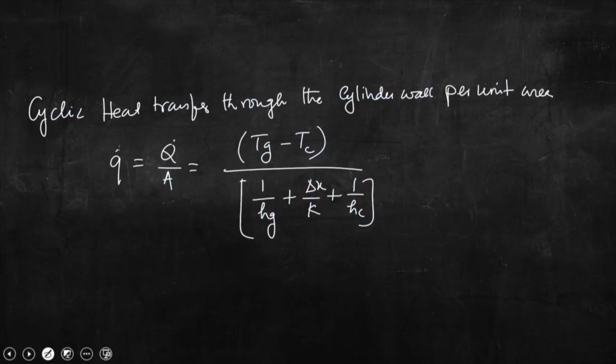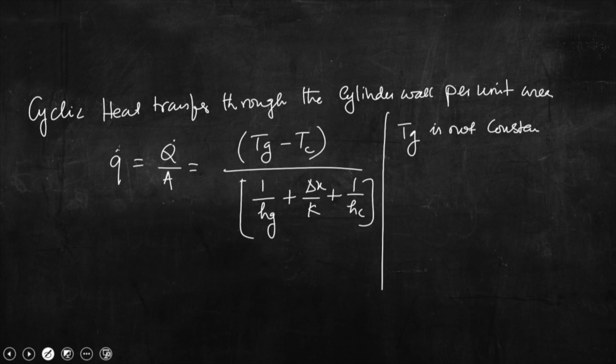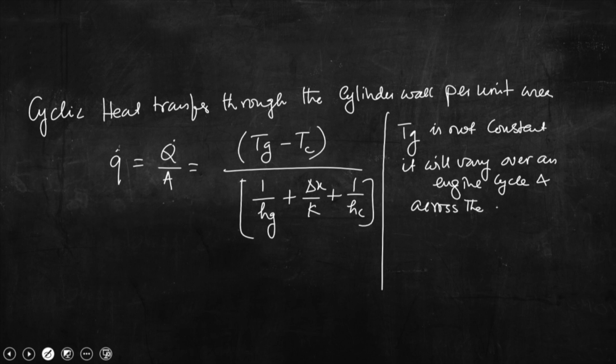So, this T g is not constant, it will vary over an engine cycle and across the breadth and width of the combustion space, or let me write, it will vary over the engine cycle and within the cylinder, right.